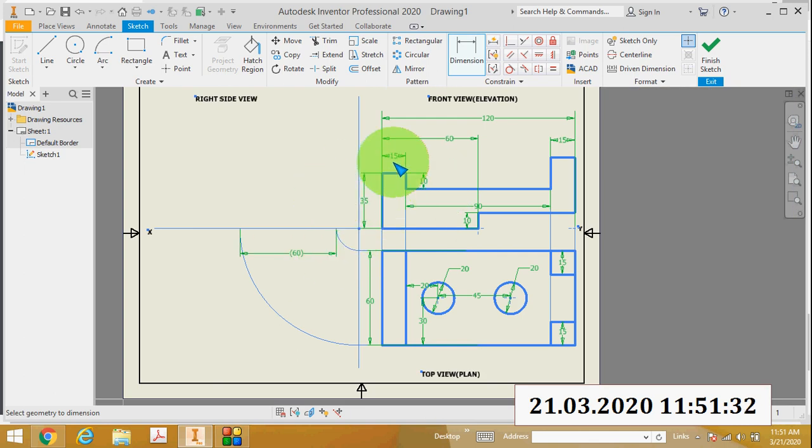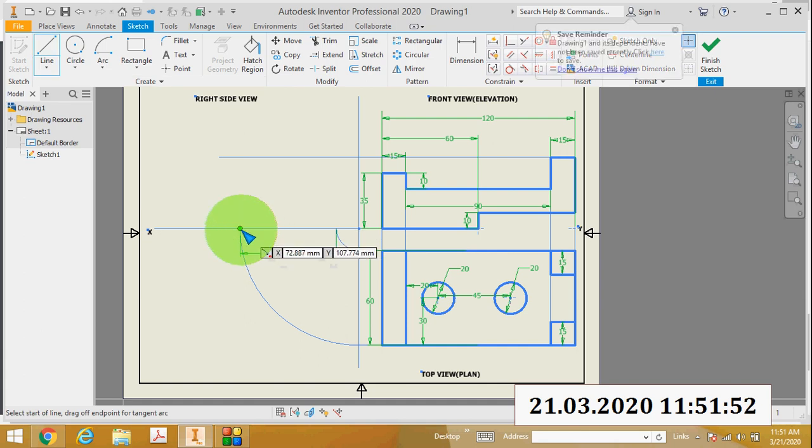So what is the height? If you want to get the height, you just project the front view. You only see which is the top point in the front view. So this is the top point. From this top point, project a line. From that line you will get the height. So this is the total height in the side view. Then complete this.